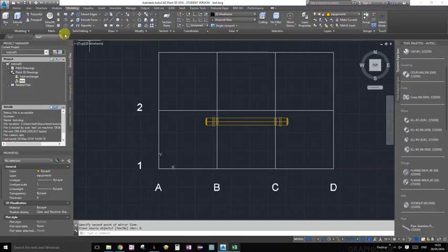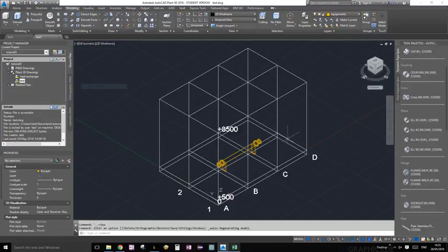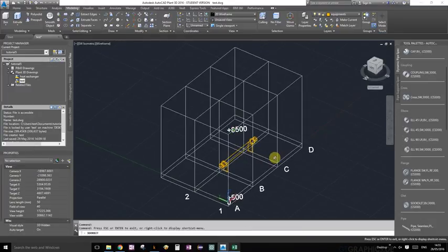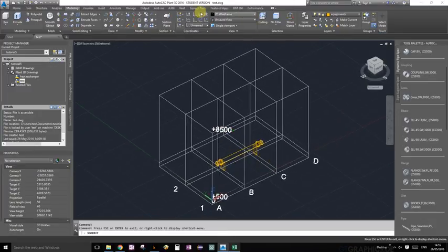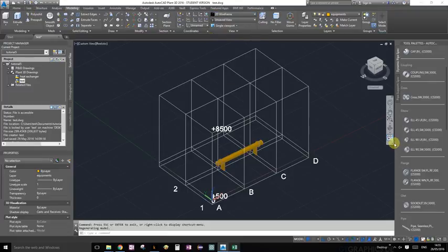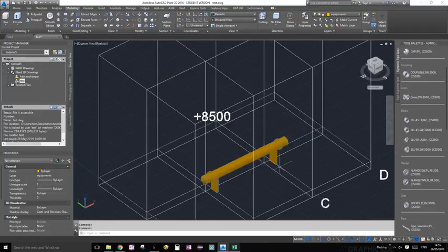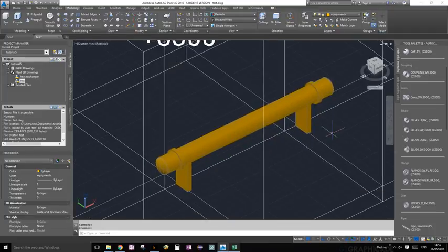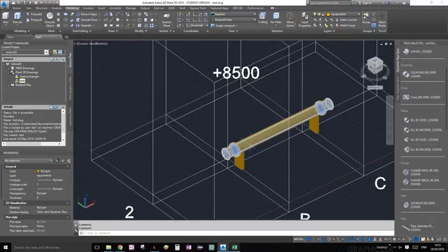Okay, let's take a look. Let's go back to the SW isometric view. Just move it a bit. And also from Modeling and the View palette, let's change it back to Realistic. As you can see, now we have our unit. Now, one thing we need to do: these are just objects right now. There's one heat exchanger and the supports, but we want to identify the entire thing as our equipment. So go ahead and select all your equipment.